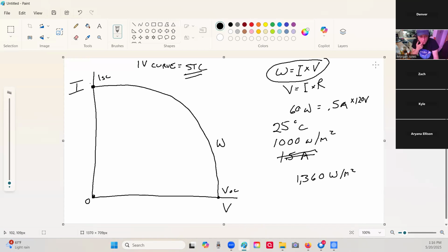So I'm going to say, okay, the maximum amps that panel could generate is the ISC. I'm going to make sure I design my wiring system to deal with the maximum theoretical amps. When it comes to volts, the National Electrical Code says that for residential, you can't exceed 600 volts for your system. So I'm going to design my system so it doesn't exceed 600 volts. Well, what volt am I using? I'm using the theoretical maximum voltage.